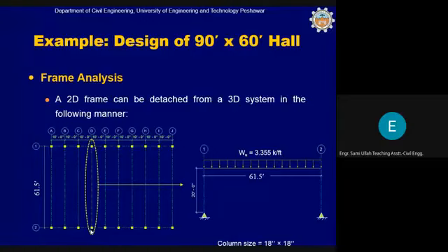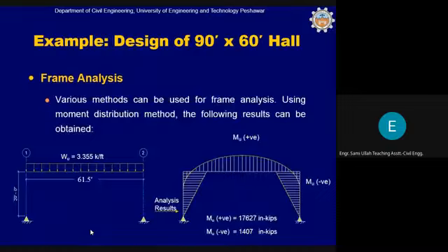Okay, so in this case, the beam is supported on columns, and the analysis will be done using a frame analysis. And you would have several times analyzed single bay frames like this, with a beam subjected to uniformly distributed load, and then the storey on a column.